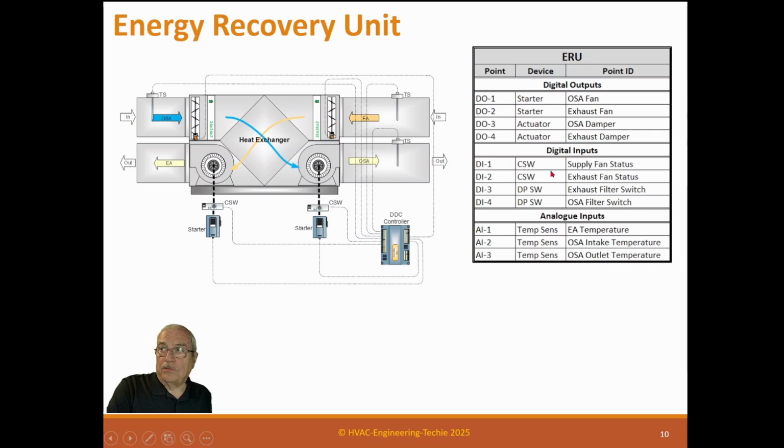And digital inputs, of course, the current status of all the fans and an exhaust filter switch and an outside air filter switch. So we basically are seeing these filters, because the one problem with these, and in the past, if you've taken my other courses on air handlers, I'm not a fan of filter switches because they don't work very well. They don't really tell you what's going on. However, in an outside air unit, filter switches are important.